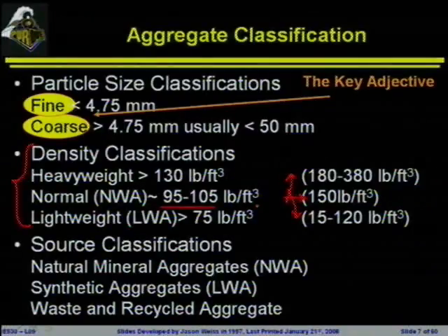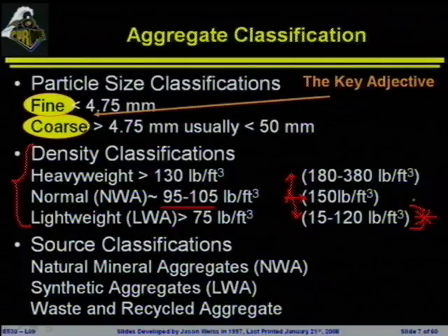The other thing that I will point out here is there is a dramatic excitement going on in the industry, especially the lightweight aggregate producers have found out that there are benefits to curing concrete when they use lightweight aggregate. We'll talk a little bit about this later on in the semester. So there's a lot of people using lightweight aggregate or other types of materials that they can actually either make the material sound absorbing or they can make the material self-curing, internal curing. We'll talk a little bit more about this later on in the semester.